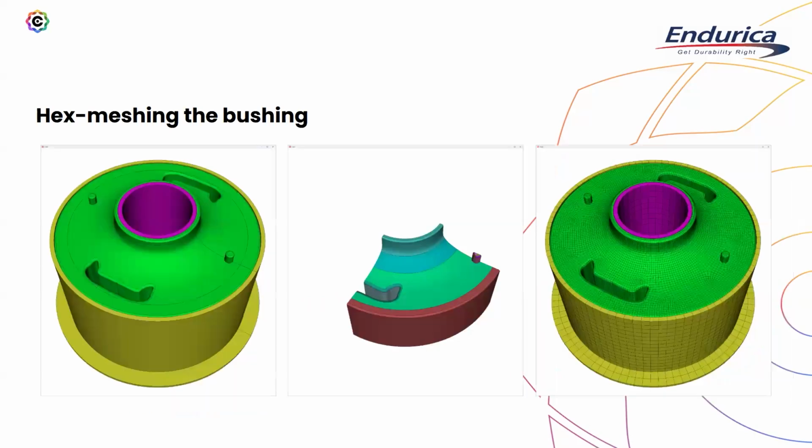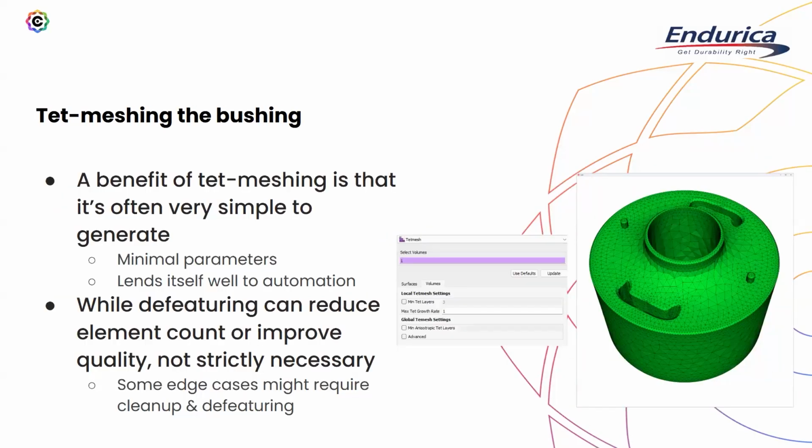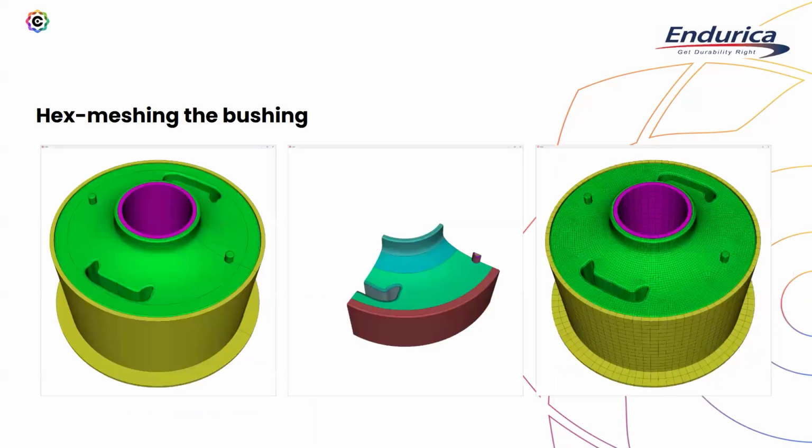As we're going to show, though, that oftentimes can lead to overly computationally intensive problems, and maybe is not quite as automatic as it might at first seem. So we're also going to show hexahedral meshing, and we'll compare the results between hex and tet meshing.